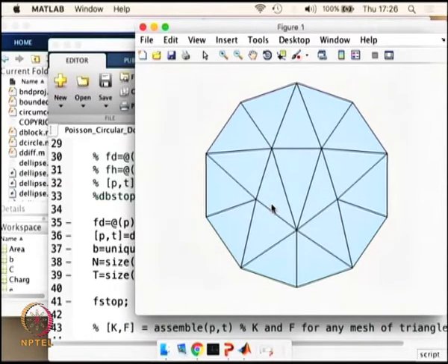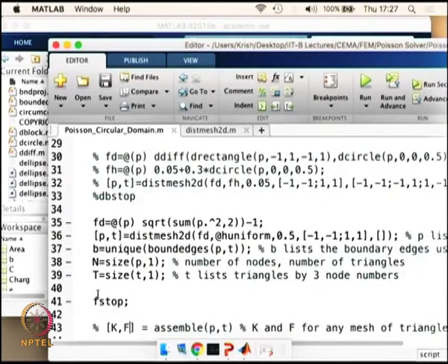And of course what you also see is that the domain is no longer so far from circular. In the initial case it was really bad, but here you see that it's conforming more and more to the circular area. So I'm going to keep 0.5 as my maximum edge length, run the code without stopping it, and then see what the result of the simulation is.